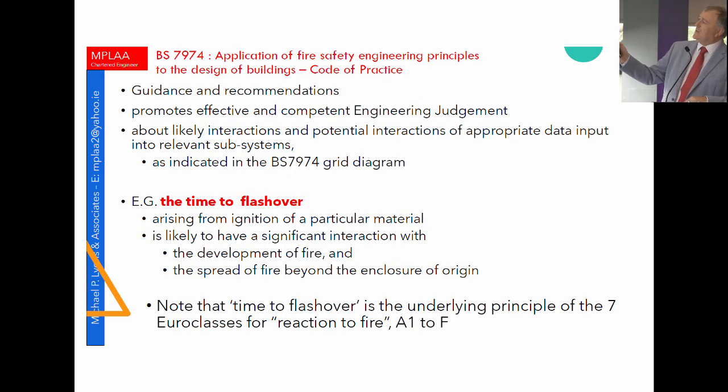In a performance-based design, one of the fundamental things is this thing of time to flashover. And it's important to note that time to flashover is both the basis for our classification of combustible materials in the reaction to fire standards that were mentioned earlier, and also in the Eurocodes.